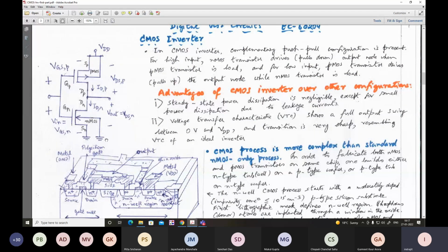Those two PN plus junctions conduct leakage currents, that means when they are reverse biased, still some current flows. They are very negligible, but with the increase of temperature and other ambient conditions, the leakage current can become not insignificant, and some power dissipation can take place.